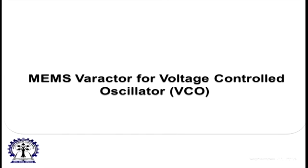I am working with a 180 nanometer digital CMOS process to make the cost of the chip much lower. But my desire is to make the phase noise performance less than minus 120 dBc at 1 megahertz offset, that too by consuming less than 5 milliwatt power. It is not an easy task.